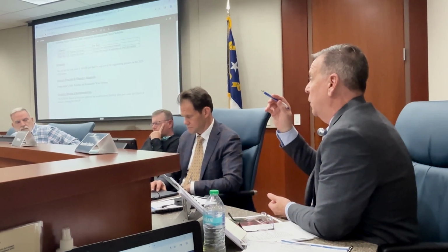We, as an organization, have not been trained to do unidirectional flushing. It's been around for many, many years, and it's very beneficial, as you saw from the presentation this evening. We need help and training on how to do this. We will have to rely on some consulting in the future to help us with the model. Models have software for UDF that we can import all this information, and it will help us tell what sequence we need to do as far as closing all those valves and doing the flushing.